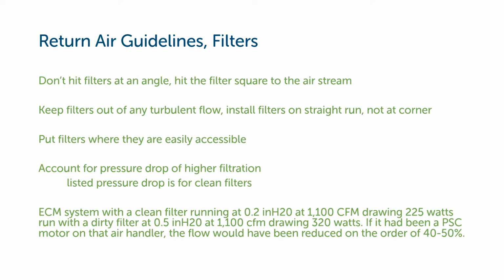We have to account for the pressure drop if we're going to upgrade the filtration on a system. We will want to make sure that the system has enough ability to overcome the static pressure of the higher filtration media. An ECM blower will use more energy to keep the flow rate up, and a PSC motor will lose CFM. And this is in regard to dirty filters.